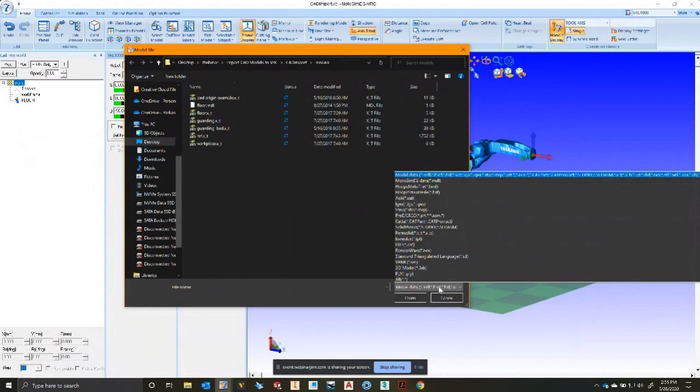So we highly recommend that when you import a file type that you're going to use for CAM function, it's only the part you're going to work on, not the fixture, not anything else in the simulation, just that one part. It's not going to break anything. It's just going to make your sim quite large. And if you're doing a lot of simulations, that could eat up your storage. So just take note of that.